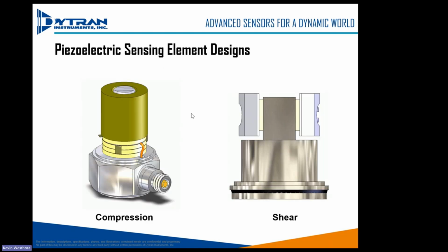This is what's inside of an accelerometer. We make both compression mode and shear mode designs. Today, 90% of all of our accelerometers are shear mode. We still do offer the compression mode design because it's very robust. We use these for industrial applications and for shock applications.